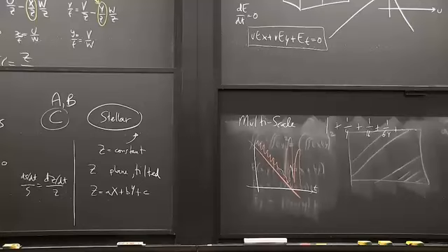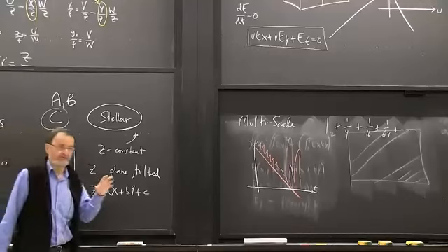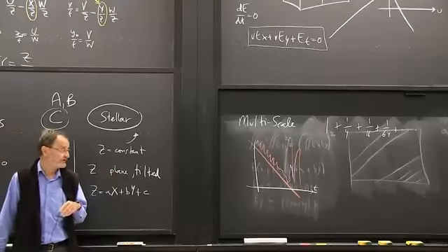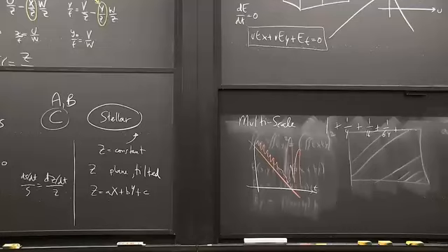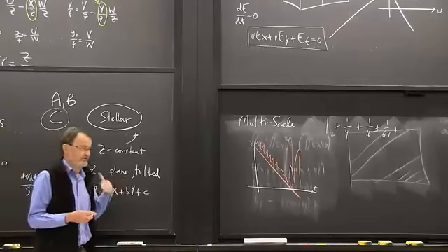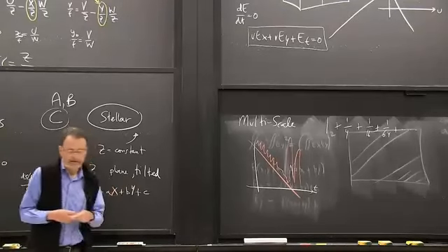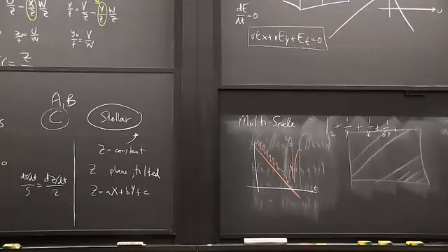You could subsample by, I don't know, square root of 2, which is less aggressive and introduces fewer artifacts. But for the moment, we'll ignore that and just take the very simple idea of 2 by 2 block averaging, which is a crude form of low-pass filtering. And it doesn't do exactly what you need to do, but it suppresses some of the high-frequency content. And while there will be aliasing artifacts, they'll be greatly reduced. And that's such a simple method to implement, and it works pretty well.